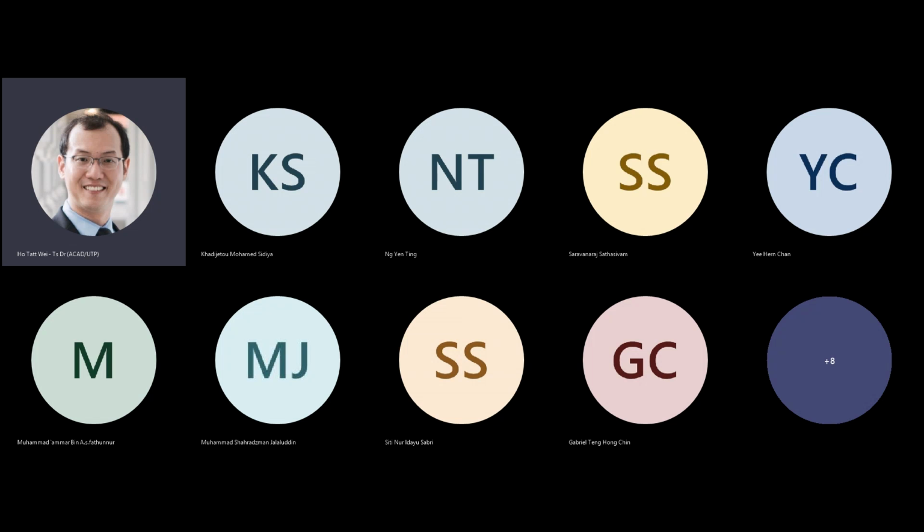But during the fabrication process, we intentionally disrupt the regular periodic lattice structure of this material by injecting impurities into that region. There's a small patch, a small volume, where we inject impurities. These impurities end up in between the lattices of the silicon, and it has the effect of either dislodging some electrons or creating additional voids, locations where electrons can get trapped. The voids are called holes. And if you dislodge, then you have electrons.